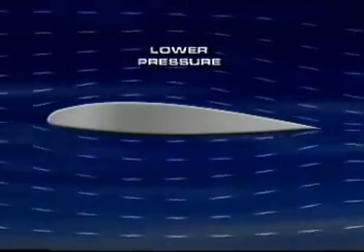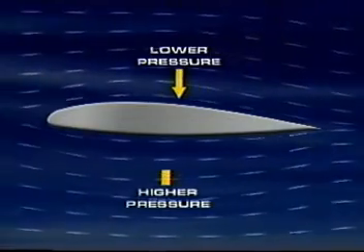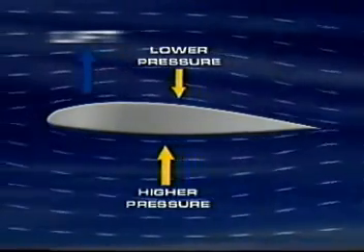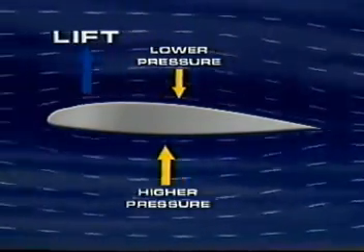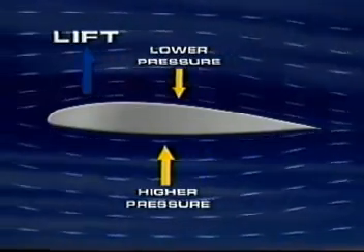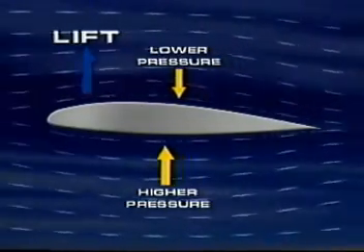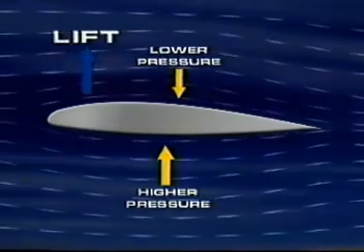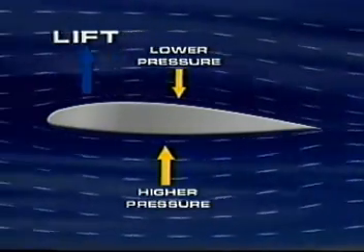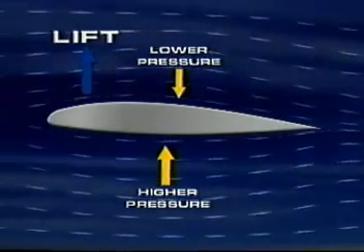Let's get into the theory of the airfoil to see how it works, diving into the aerodynamic aspects of the jets. To produce lift, the wing must pass through the air in such a way as to accelerate the air on the top of the wing to a speed higher than the air passing under the lower wing surface. The difference in relative pressure will result in an upward suction, the lift vector. The greater the difference in the lower and upper surface airspeed, the higher the difference in pressure. Hence, the larger the lift vector.